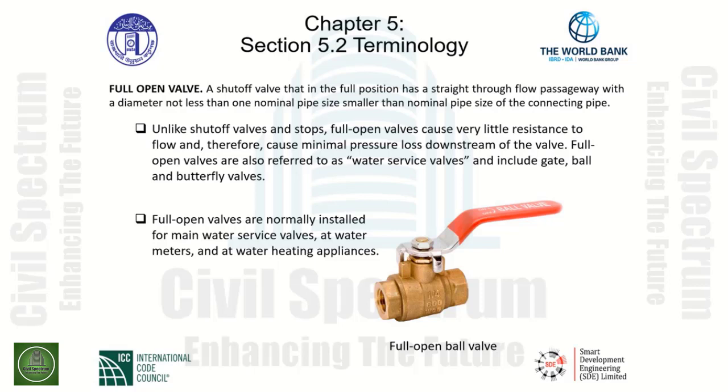Full open valves are also referred to as water service valves, and they include gate valves, ball valves, and butterfly valves. Full open valves are normally installed for main water service valves, normally installed at water meters, and at water heating appliances.